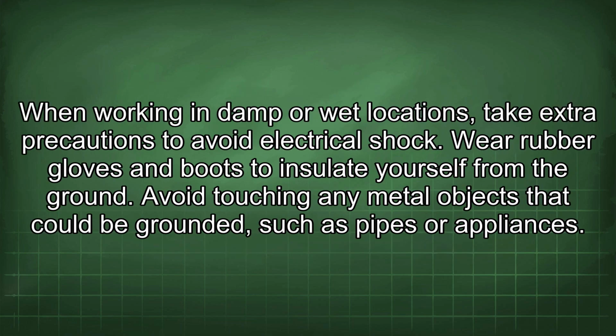When working in damp or wet locations, take extra precautions to avoid electrical shock. Wear rubber gloves and boots to insulate yourself from the ground. Avoid touching any metal objects that could be grounded, such as pipes or appliances.